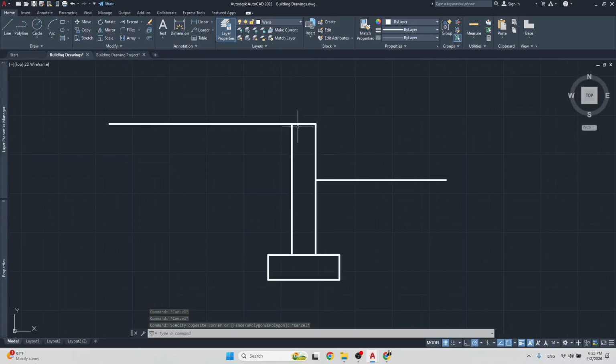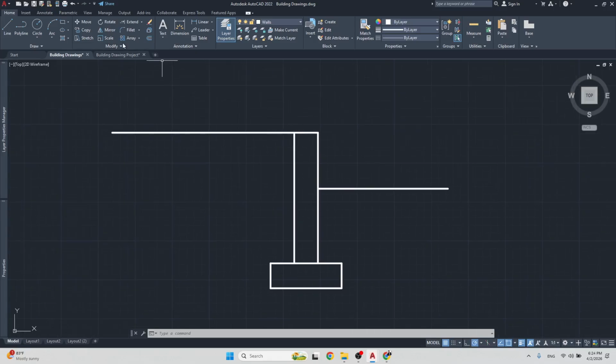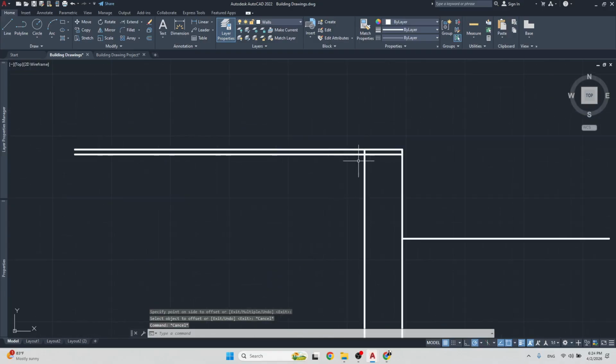So what we need now is to first show the different layers. So we have the finished floor, which is like plaster. When you plaster a wall, well, you kind of plaster the floor also, and that is going to be resting on top of the floor slab. So let's say this is about 18 or 25 millimeters or 1 inch thick. So we're going to offset 25 millimeters, come down. All right, so something to note right here,